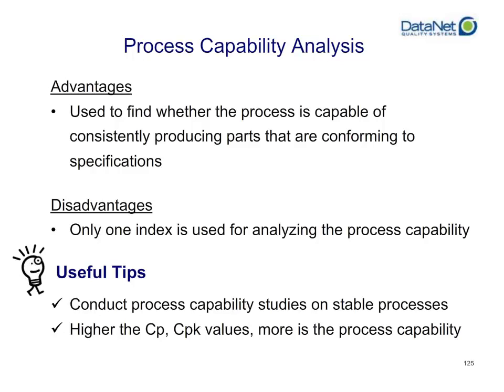You need to be able to both say, is CP high? If so, is it close to CPK? And then whether or not it is, you want to be looking at the control charts and the histograms to see where that actually falls. You also want to be able to compare the way it is now versus how it has been in the past to see if you're improving or getting worse. You can only run these capability parameters, the CP and CPK, if your process is statistically stable, meaning your process is currently in control and has been fairly in control for the data set you're running the capability analysis on. In general, the higher the CP and CPK values, the more capable your process actually is.